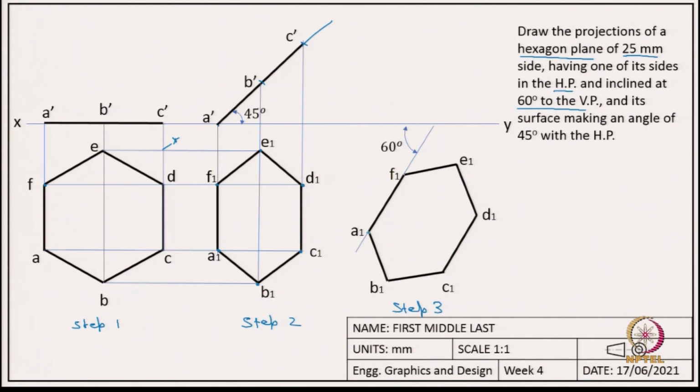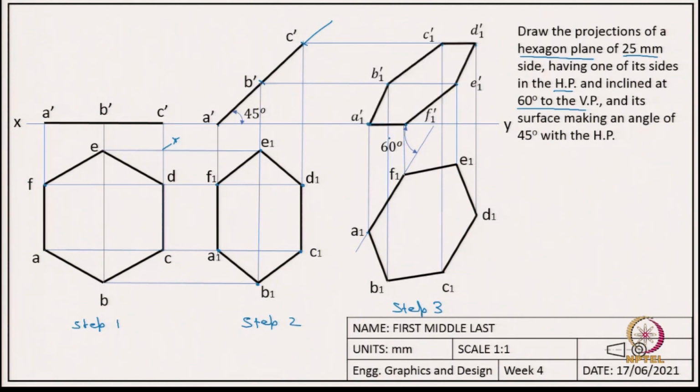If point A1 is here, we need a vertical projector which connects with the front view A from the previous step. Here are the projection lines, and the intersections define the points we are looking for.